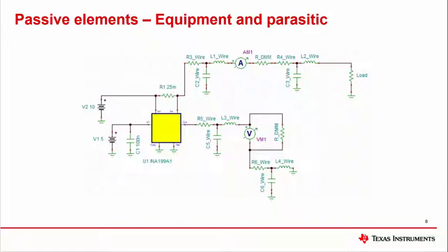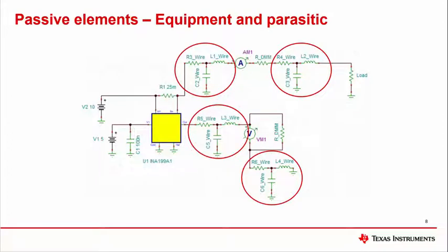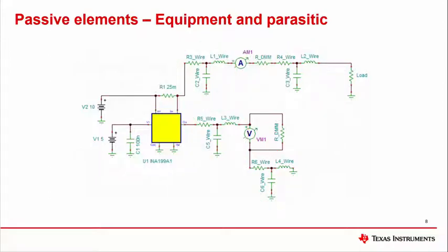Common parasitic elements introduced to circuits come from banana jacks, alligator clips, and any other connector. Connectors will have their parasitic values on their datasheet. In addition to the connectors, the wires used to make outside connections will introduce parasitic elements usually determined by the type of wire and its length. Other passive elements can be present when using equipment as previously discussed. All equipment will introduce passive elements to the circuit under test when connected. The importance of these passive elements depends on the accuracy needed, as lower cost equipment will have less accuracy and worse performance, while higher cost equipment will have higher accuracy and better performance.